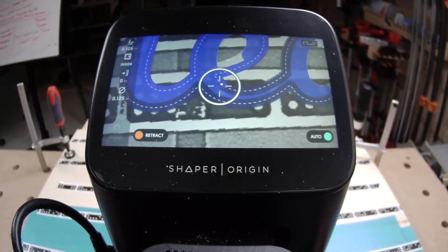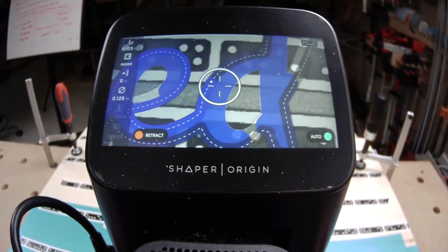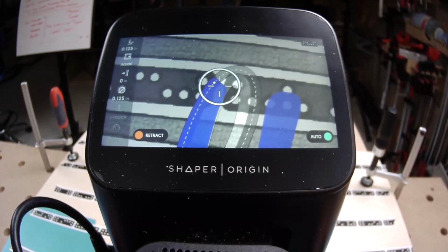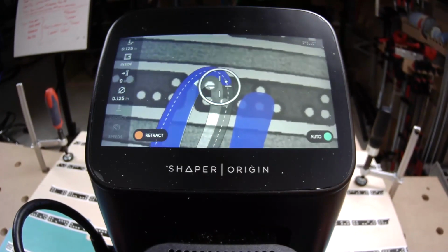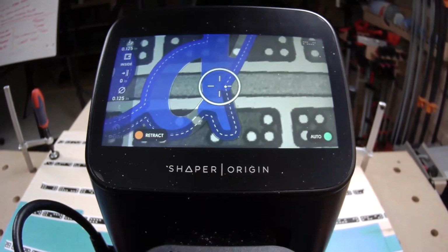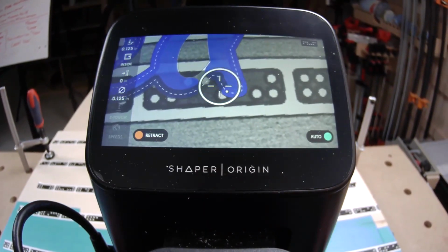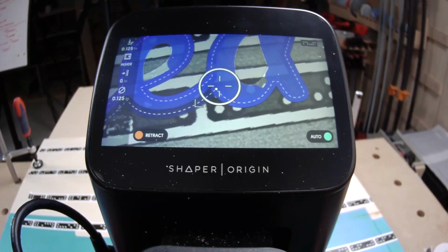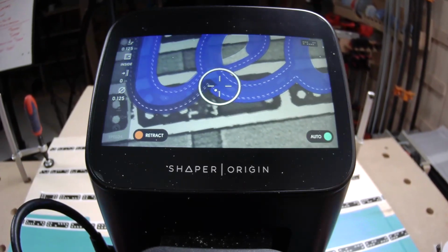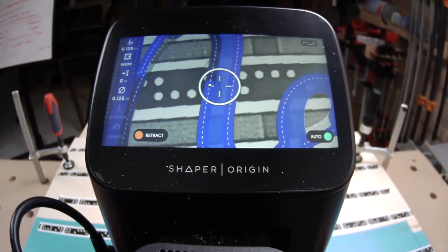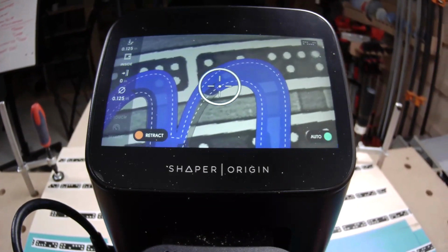Down cutting router bits are definitely an intermediate to advanced router bit to use, but when the application is right, there's really no replacing it. I also really love down cutting router bits for really thin commercial veneers. We did a show with Ramon Valdez months ago, last year probably at this point, about cutting inlay and marquetry with Origin using super thin 1/42 of an inch commercial veneers.